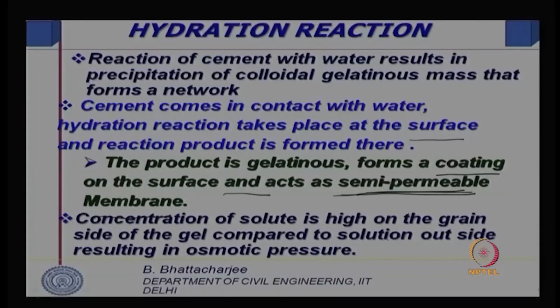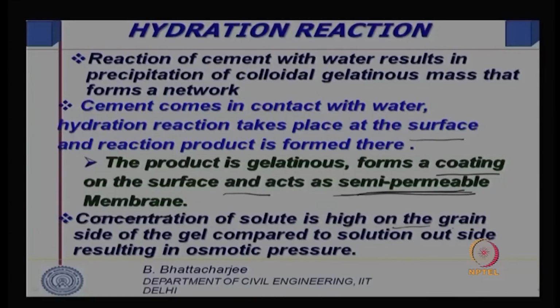Anyway, at the moment we understand that there will be an osmotic pressure created on the grain side, and that will result in rupture, breakage of the semi permeable membrane, and water will penetrate into the unhydrated portion of the cement, and thereby the hydration reaction would progress. So, concentration of solute is high on the grain side of the gel compared to the solution outside, resulting in osmotic pressure,